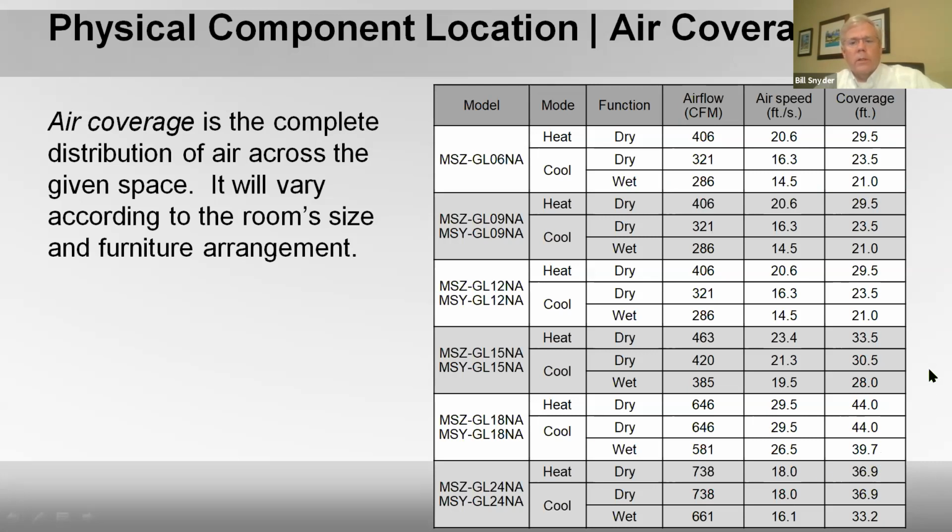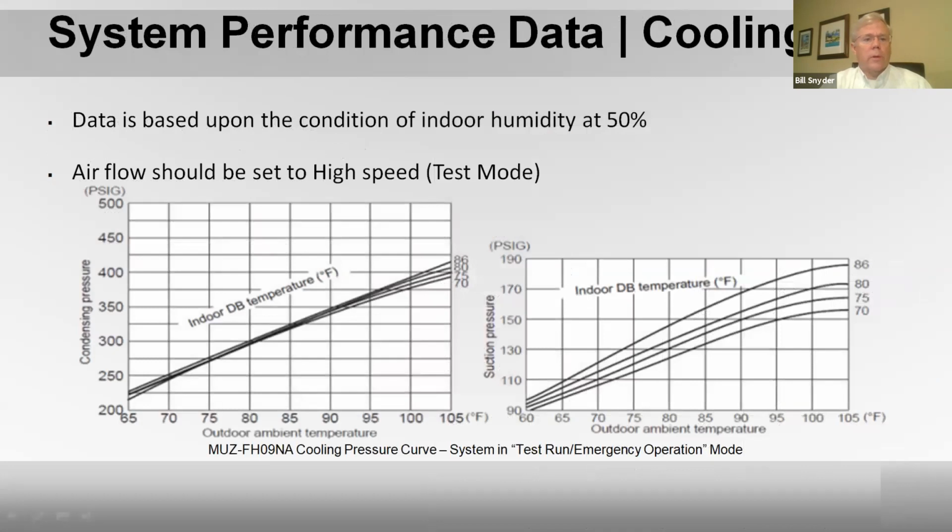So it's just something to consider. In most cases, the rooms are small enough, less than 21 feet, not a big issue. But if you're getting into a big great room or commercial application where you want to make sure you move enough air, you want to take a look at a chart like this and determine it. These charts can be found in the service guide.